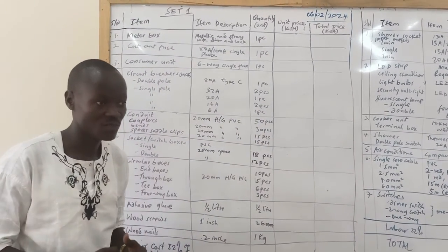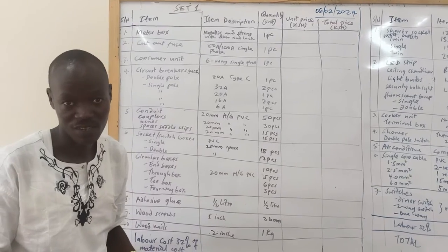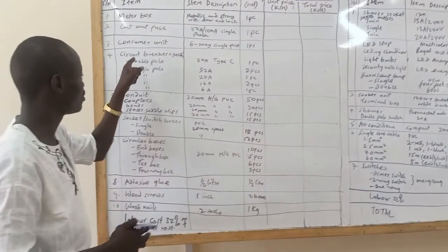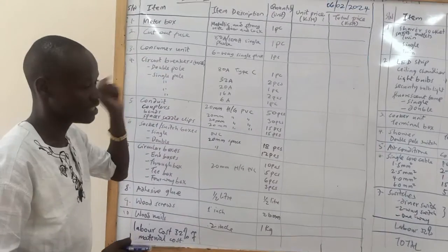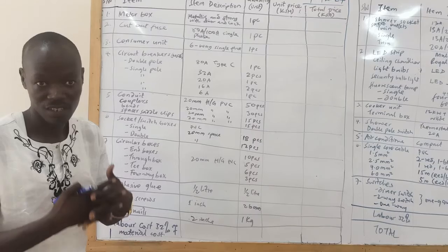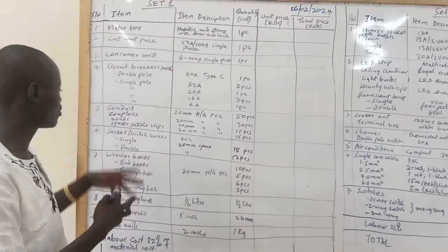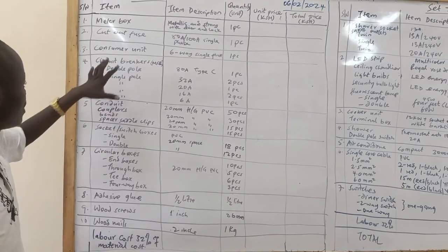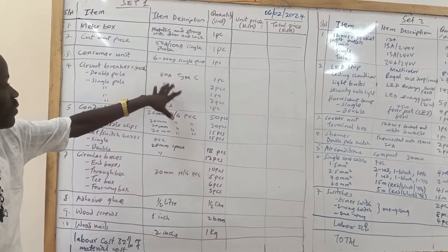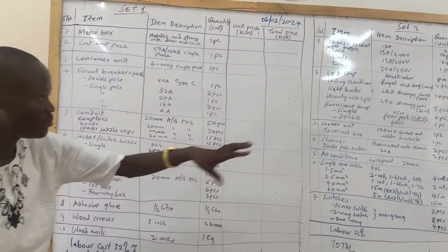It's good when you're buying the consumer unit, buy it with appropriate circuit breakers at first. Even though you're not going to install them immediately, buy them, because you need to install the consumer control unit on the wall also during the first phase, which is the mounting of the conduits. You also need conduits, as you can see, broken down, and all these are not coming from heaven, they are coming from our design, the way we did when we were sizing.